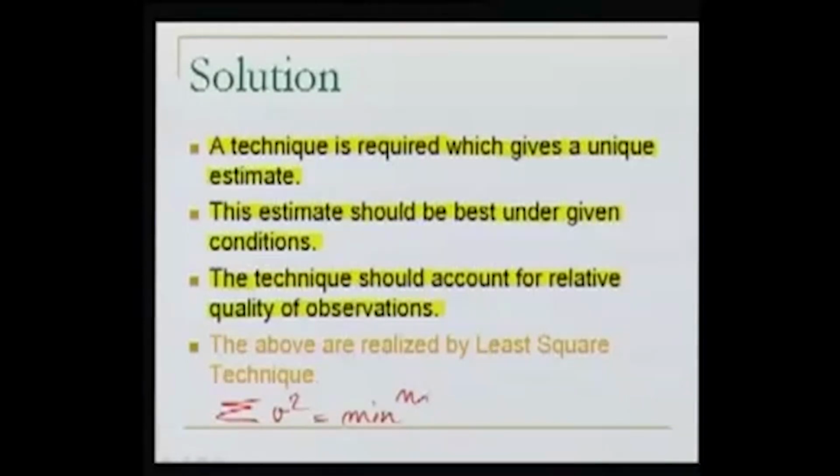Now this is also very important. We know about that stochastic model. Depending, we took 3 observations, x1, x2 and x3. If we have some idea about the precision of these observations, the weight that we can give to these observations, we should take that weight also into account.